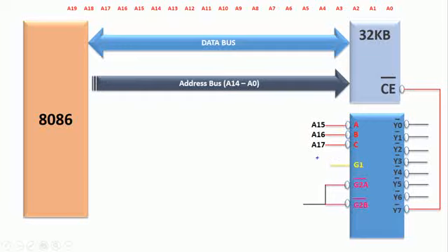Depending on the bit position, the address space mapped, meaning the address range allocated for this particular device, is going to vary. Here I'll make use of A18. I'll go in the order. For simplicity in this initial class, I'm going with A18, and after that I'll take A19 over here. So this is another kind of interfacing diagram.